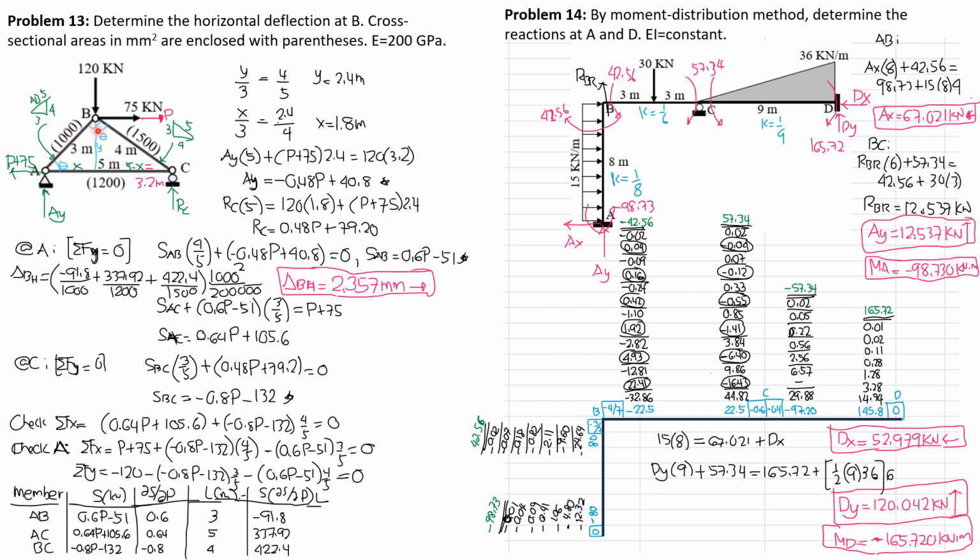So, perpendicular at this vertex B here, so that's 90 degrees. So if I call this theta, drop a vertical line, so this is also theta. We have similar triangles. So from the figure, y is to hypotenuse for this right triangle, opposite of theta as to hypotenuse. So y is to 3, hypotenuse, equals, for this big triangle, opposite of theta is 4 and hypotenuse is 5. So 4 over 5. That's why y is 2.4 meters.